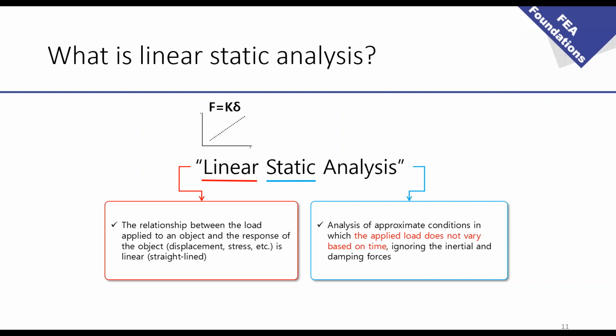It's static because the applied load does not vary based on the time, and you are ignoring the inertial and damping forces. So what does it mean? It means basically that when you apply the load in linear static, the load is applied so slowly that the model doesn't feel the moment when you apply the load, and you can consider that the load is always applied on the model uniformly and it doesn't depend on the time. So you are ignoring the moment where you apply the load. This is why it's called static. So it actually doesn't move. That's the thing. It's static.